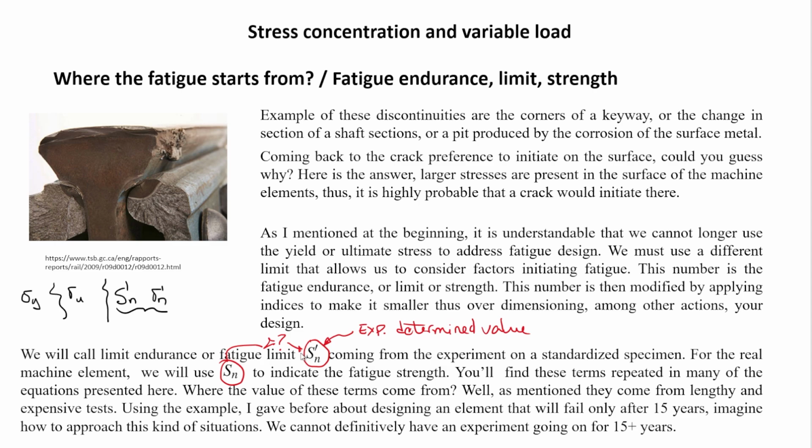Then the question would be, okay, but how do I calculate that? If I make a comparison between what we did in static design and this variable load design, I know that in the past, depending on whether the material is ductile or brittle, I used the Tresca or von Mises failure theory. So is there something similar for stresses? Well, the answer is yes.